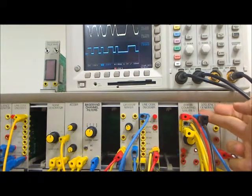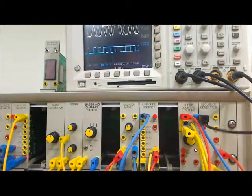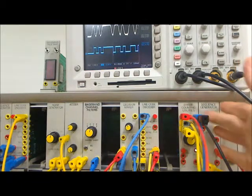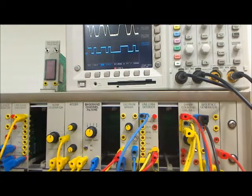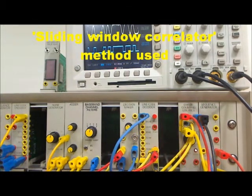So coming from the output of the exclusive OR is a signal which is a series of pulses corresponding to the errors that I've detected. So now we'll take a lead from the output of the error utilities. We'll take this lead and we'll put it into the pulse counter down on the master system.